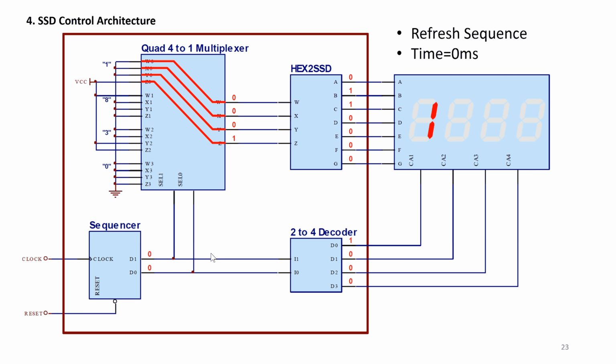Now, if you remember back earlier on, we talked about a refresh sequence or refresh architecture that would be needed to power on your 7-segment displays. Given these 4 components, this would be the output. As you can see on your right, you have your 4 7-segment displays with their own common anodes, as well as the common cathodes, which are your 7 segments itself.